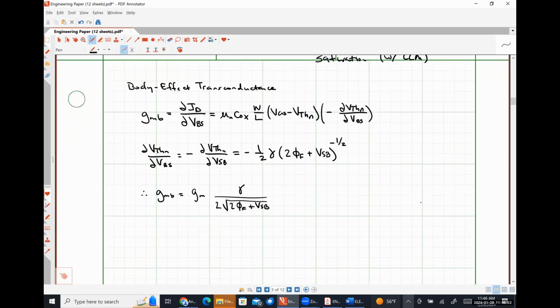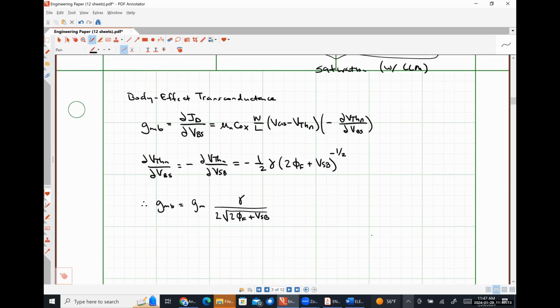All right, so we covered our transconductances similar to how we covered the transconductance for BJT. The next thing that we talked about in the BJT was the linear relationship between our base current and our voltage VBE, right? Which was how the resistance R pi came about. Does our gate current change with VGS in a MOSFET? Does our gate current exist? Not really, no.